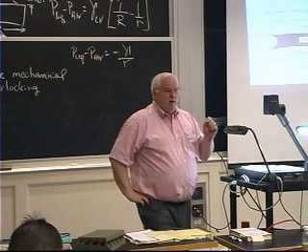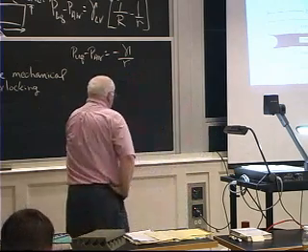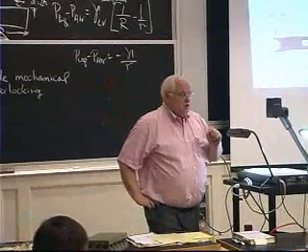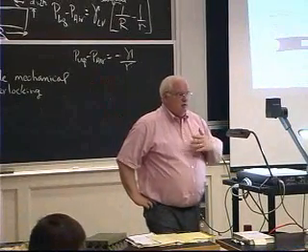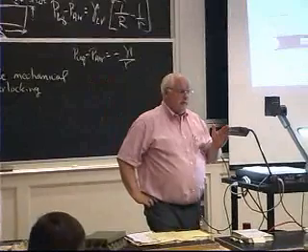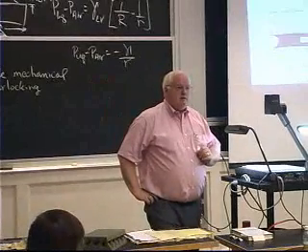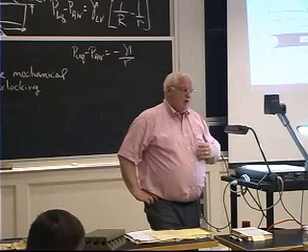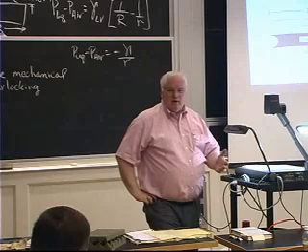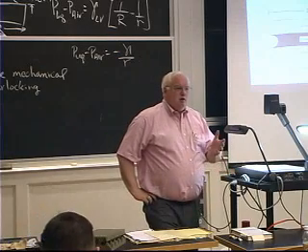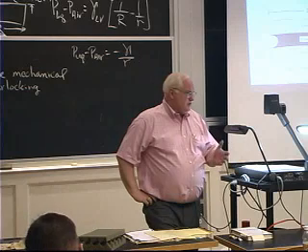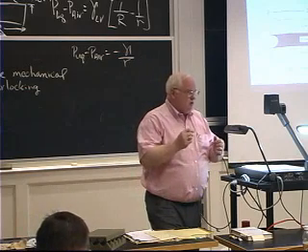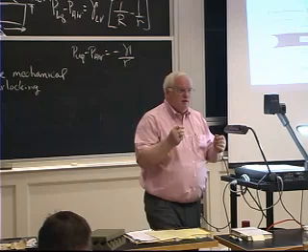accuracy. If I'm machining something, a 1-inch diameter bar, and I'm holding it to 1/1000th of an inch, which even I could do in the laboratory, okay, that's 1 part in 1,000. If I hold it to 5/10,000ths, which I may or may not be able to do in the laboratory, but a good machinist can hold 5/10,000ths. That's 1 part in 2,000 in terms of accuracy, precision. And you know, if you ever use vernier calipers or micrometers, that's kind of what you get in